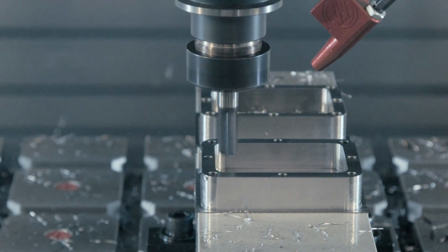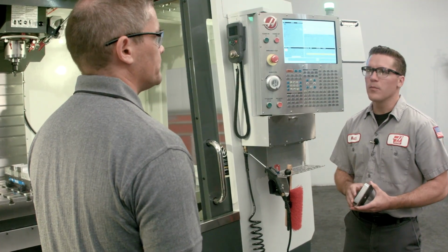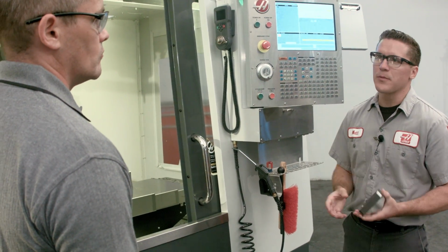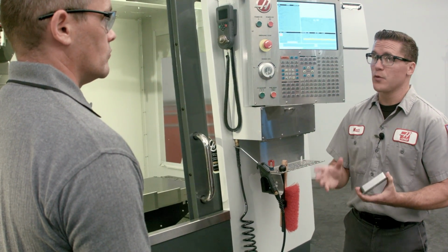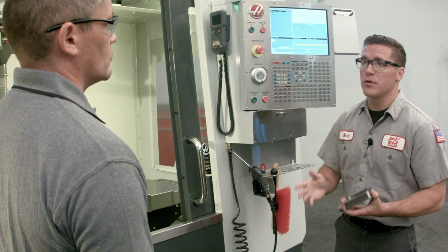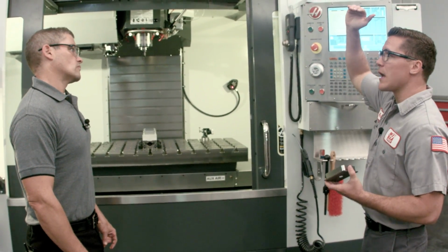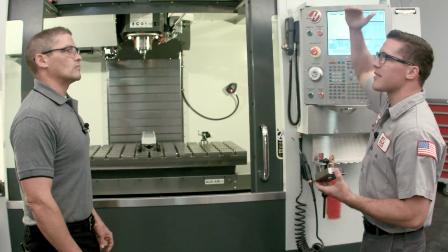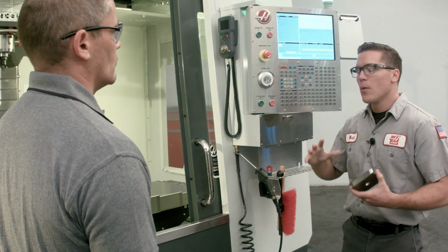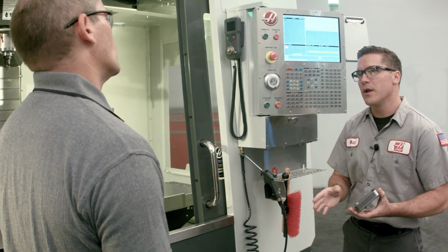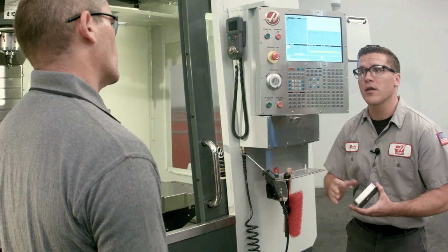One of the tips to getting the most out of MQL is selecting a cutting process and a tool that's going to move heat away from the cut. Yes, moving heat away allows the tool to stabilize to an acceptable cutting temperature. And with optimization, this can even lead to improved tool life. One of the potential problems when using flood coolant is thermal shock to the tool. The tool heats up rapidly in the cutting zone and then cools down rapidly, and then heats up and then cools down rapidly. With MQL, you don't have that problem. The oil mist keeps frictional heat to a minimum, and the tool temperature stays constant.